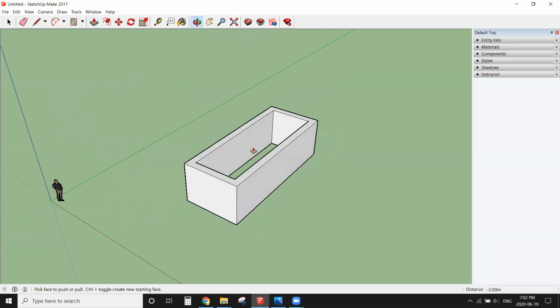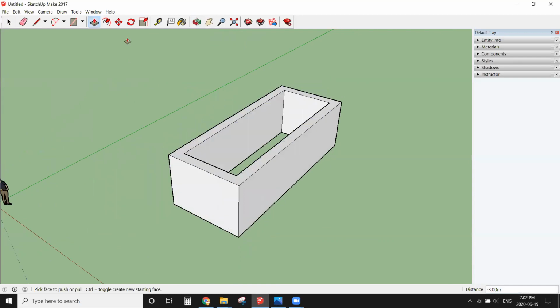So now I want to add a roof, and let's add an arched roof since we know how to create an arch. So again, I'm going to go to 2-point arc. You can click the little nodes where the corners line up on this shape you've created. So if I click one node, I can come over and click the other node.